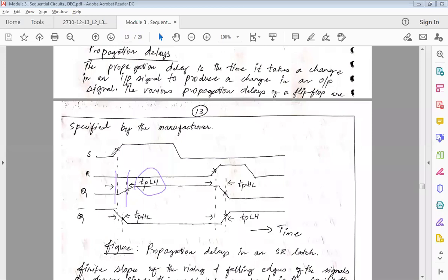Low value is 0 here. So, sir, the propagation delay is always taken with reference to the base. Propagation delay, you can take it at any point of time. This becomes easy for us to analyze. Because I'm taking a slant line here, I will know that this is my midpoint, right? And from here, I will draw a line. And here also, it should have been here, but there is a shift here. So it's easy for me to understand because it's a slope, right? If it's a straight line, then there's no point in comparing two straight lines, isn't it?